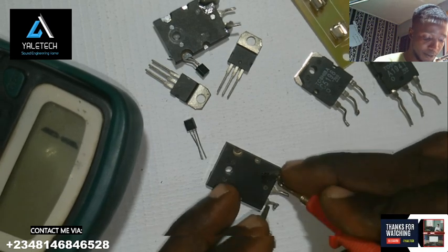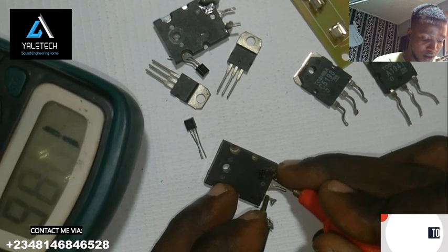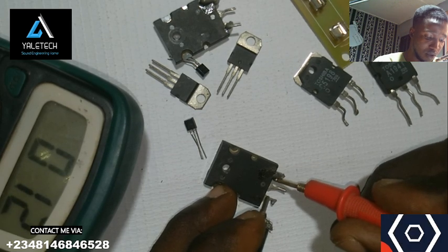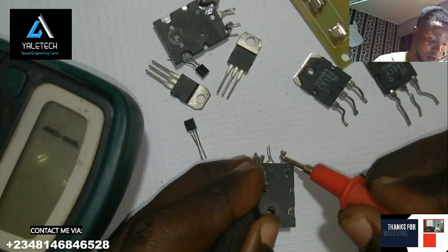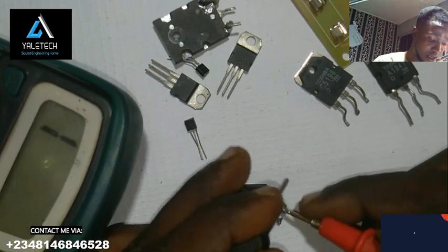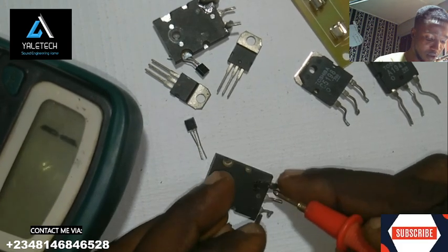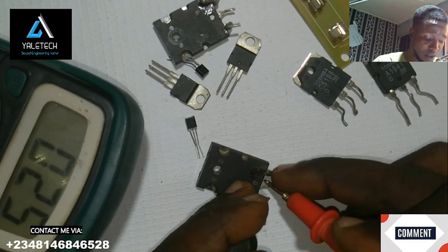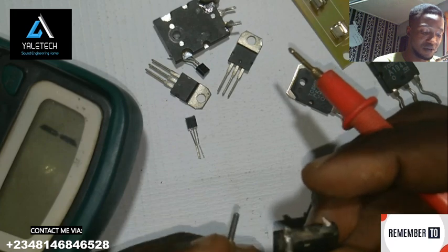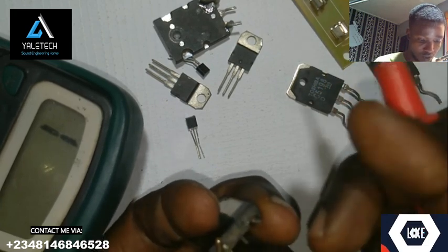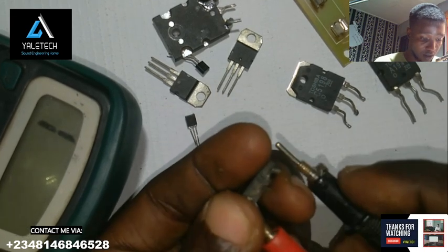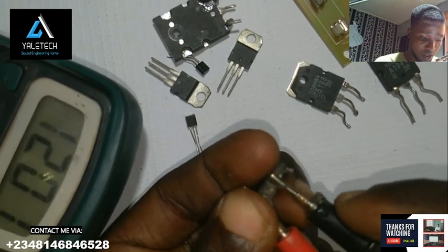All right. So see it now. Making noise in this direction. Let's see the other way around. You see? So this direction, this side again. So it's short already. But let's confirm further. Rubbish. So you can see this transistor is bad because it's giving reading in all directions, which ought not to be so. You can see it. If I invert it, the same thing, the same thing.